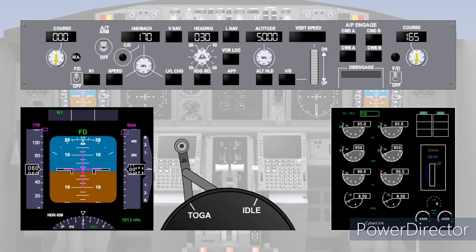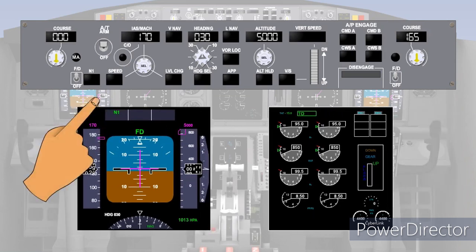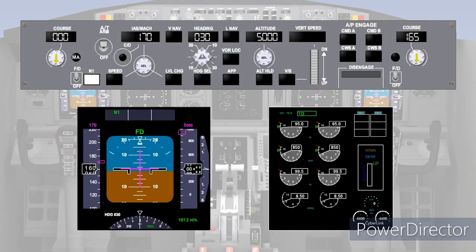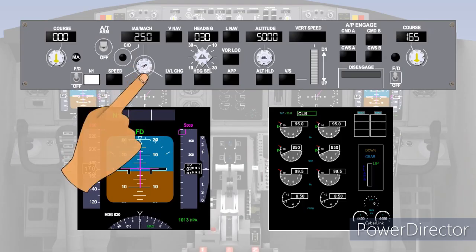After 60 knots, the autothrottle will hold the levers at that position to maintain the selected value and to prevent the system from chasing any slight variation in N1 or EPR during the takeoff. After takeoff, at 400 feet above ground level, the autothrottle N1 button is pressed, and the commanded thrust reverts from takeoff to climb, annunciated on the engine instrument display. The speed selector can be used to increase the reference speed to 250 knots.